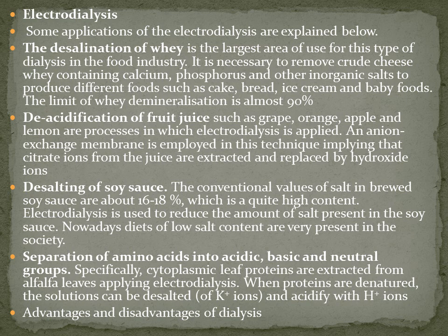the food industry. It is necessary to remove inorganic salts from the crude cheese whey containing calcium, phosphorus and others, to produce different foods such as cake, bread, ice cream, baby foods, etc. Deacidification of fruit juice: juices such as grape, orange, apple and lemon are processed in which electrodialysis is applied. An anion exchange membrane is employed in this technique, implying that citrate ions from the juice are extracted and replaced by hydroxide ions. Desalting of soy sauce.